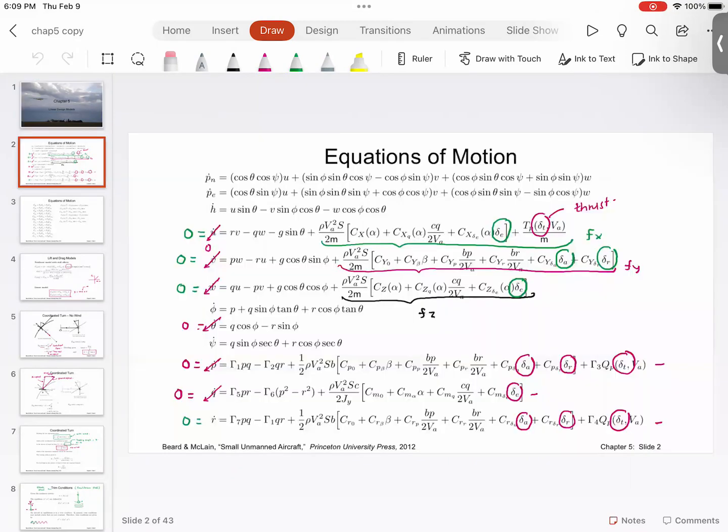So these are the equations of motion that we talked about. These equations look complex, and depending upon the flight vehicle that you are analyzing or designing or controlling, they would become more complicated. But the first line of analysis is to ignore the nonlinear terms that are contributing to very small dynamics. Then understand the operating regions. For example, if the aircraft is in level flight, or the aircraft is climbing steadily, or the quadcopter is hovering, then find out the trimming conditions.